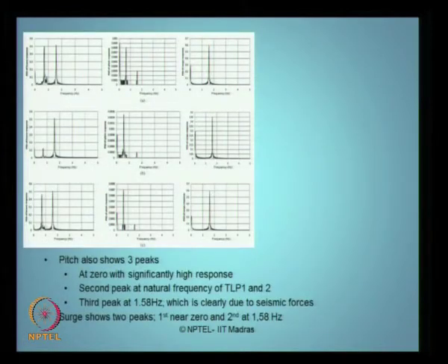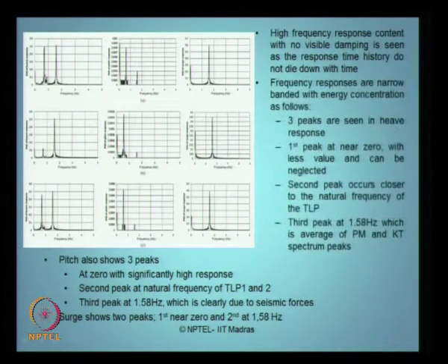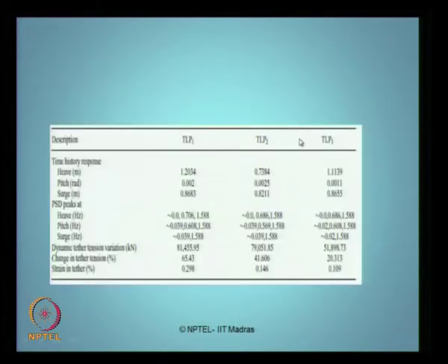So these are my power spectral density functions of the different responses in heave, pitch and surge. Of course, you can see these responses in the paper in detail. So we will quickly look at the observations. Heave frequency response content shows no visible damping, because you can see here this is not dying down,